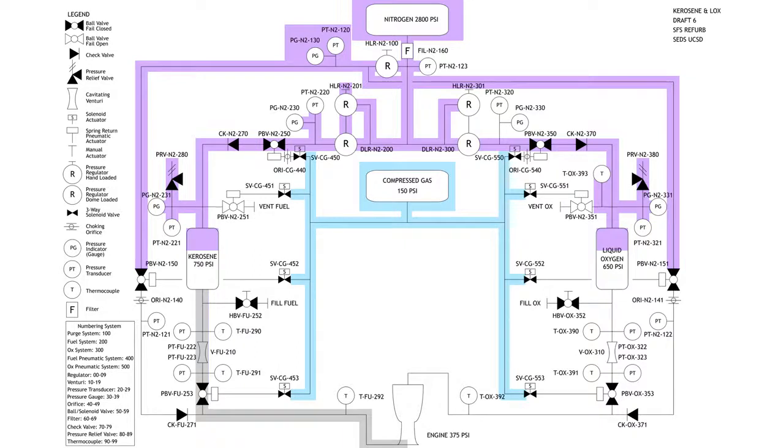So you have both the regulator and the ball valves, 250 and 350, pressurizing your tank slowly? Yes. So what happens is that the regulators let flow rate through at a fixed amount. We can't affect the regulator flow rate. What we can affect is how fast that pneumatic ball valve opens. And so we're going to open it slow. Honestly, these regulators can't go down to 5 psi. They'll probably go down to 100, so we'll start at 100. When it opens with 100 psi, it'll open pretty slowly, and that way we don't hit our propellants with a 100 psi brick.